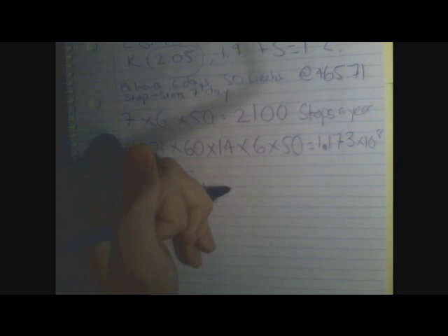So using formula 3, which is diameter cubed is equal to 10 to the power of 4 times FS divided by FR times KS times K, times the square root of the critical moment plus, this is axial load, we don't have that, so that is 0, plus 3/4 the torque squared.